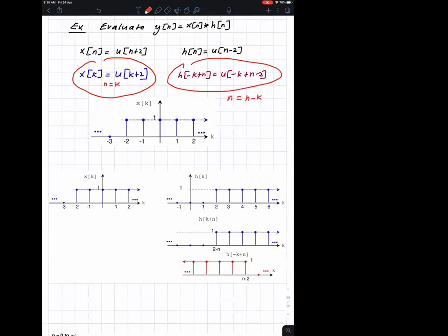That's all the difference. What this means is you have inverted the signal, and then you also have shifted the signal by n. Inverted and shifted. Then you take the sum of those products, which is shown graphically now. So this is x of k. You know how to sketch x of k, right? By now, just a discrete step signal that is shifted to the left by 2.